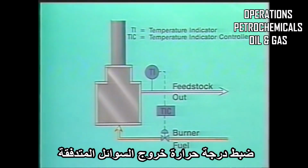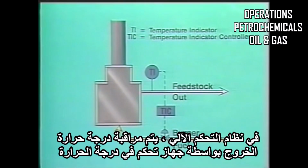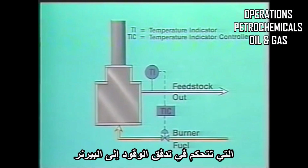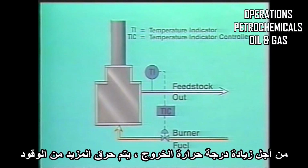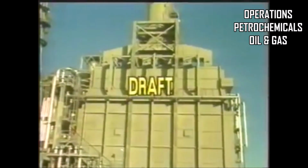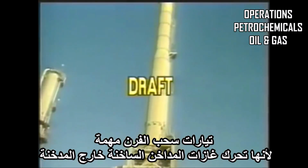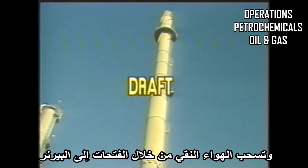There is a target outlet temperature for the process flow, and this is used to determine the amount of fuel going to the burners. In an automatic control scheme, the outlet temperature is monitored by a temperature controller, which controls the flow of fuel to the burners. In order to increase the outlet temperature, more fuel is burned. To decrease outlet temperature, less fuel is burned. The furnace draft is important because it moves hot flue gases out of the stack and draws fresh air through the registers to the burners.